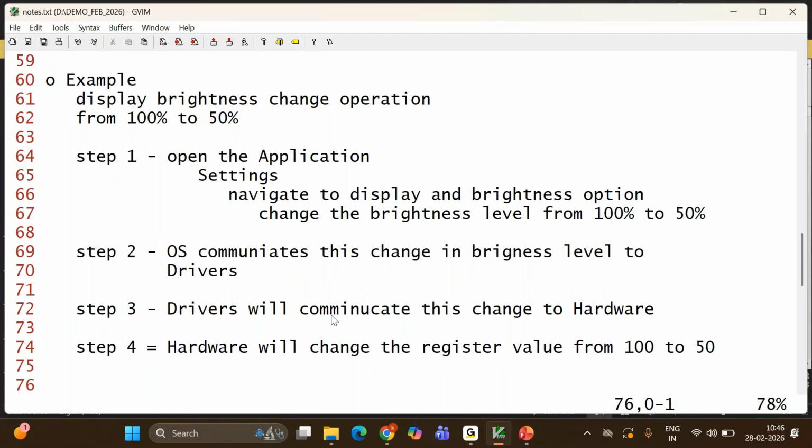So in terms of data exchange with your pen drive through USB, USB drivers will come into the picture. USB driver development, the embedded system engineer will take care of it. You need to worry about the USB controller being able to fetch the data from the memory and send it to the peripheral, such as the USB port. A USB port is a peripheral. It is present outside your chip, meaning it is present in your laptop.